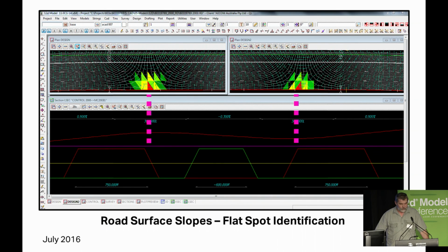The obvious locations for identifying and avoiding these flat spots are areas of zero longitudinal grade, such as crests and sags, where attempting to rotate your superelevation is never going to work and probably indicates you're not considering horizontal and vertical alignment coordination in your design anyhow. There is a more insidious situation that is difficult to identify without your superelevation diagram, and that is where a drop or rise in pavement edge levels generated through the superelevation rotation is countered by grade running in the opposite direction.